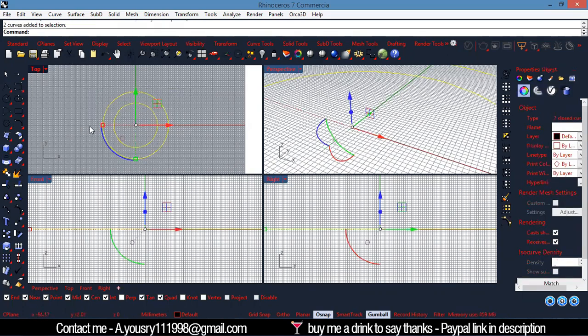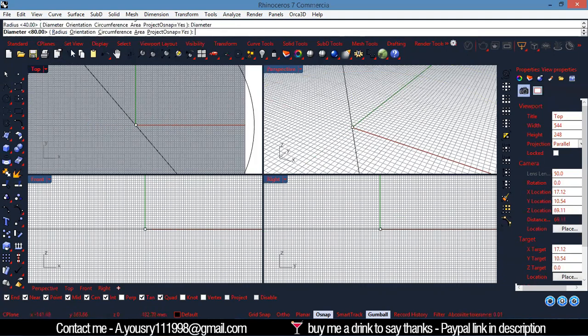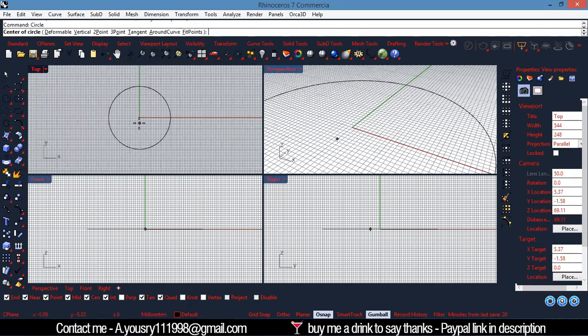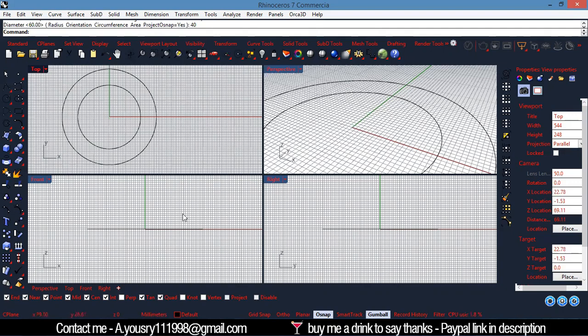So I'm going to delete those and get back again, hit circle at the origin and pick diameter. So the diameter here, the first is 60 and the other is 40. All right. While the two other circles, the first circle is going to be here, and I'll pick the radius, first is 25. All right, so that one.